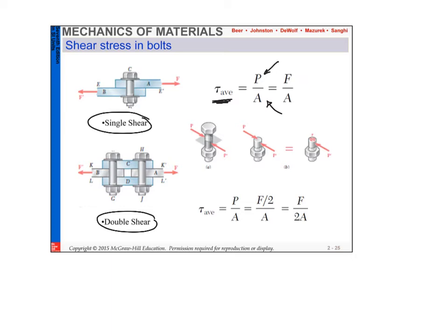In other words, you see these two bars, C and D. Those two bars feel how much of this F? How much do they see? Each bar of them will see the full F or half of F. Yeah, that's what you said at the beginning, yes. So each one of those will see F over 2.